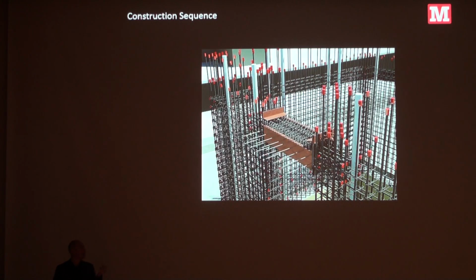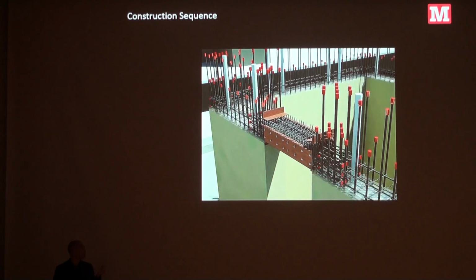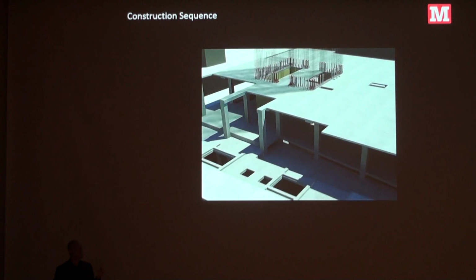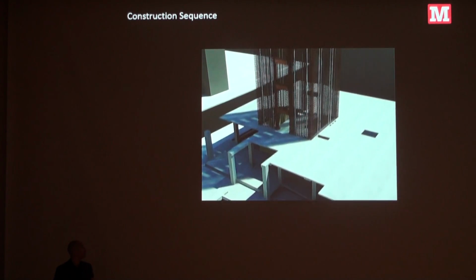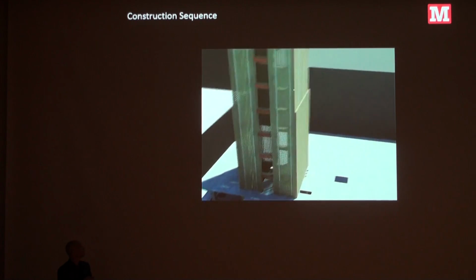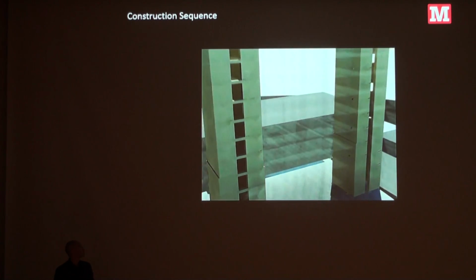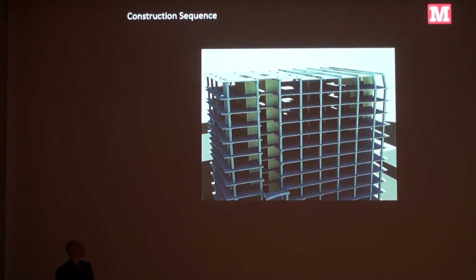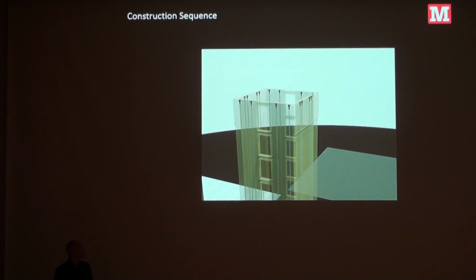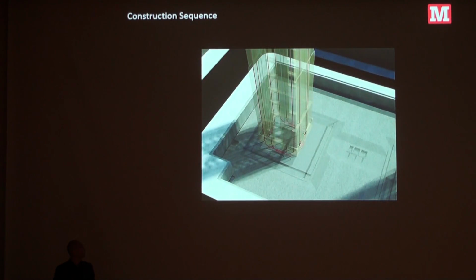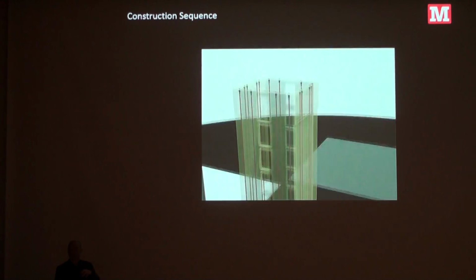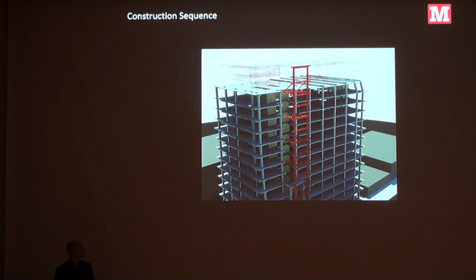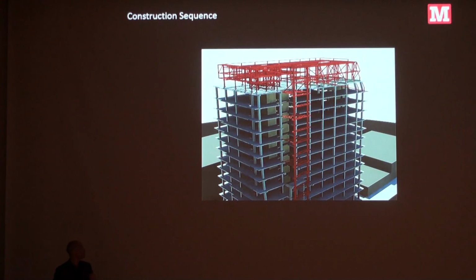This is one innovation. It's a coupling beam that's like a precast element or a steel element that flexes and dissipates energy, but it's also formwork. So we're thinking about construction process and technique with the builder. Here you see the post-tensioning ducts going up. Now we've got the two towers. What's going to come next are the vertical post-tensioning cables from the top. At this point, we're working with bridge consultants to figure out the best way to stress these things, and we pull on them. And then finally, we've got the steel framing on top, and it's clad.